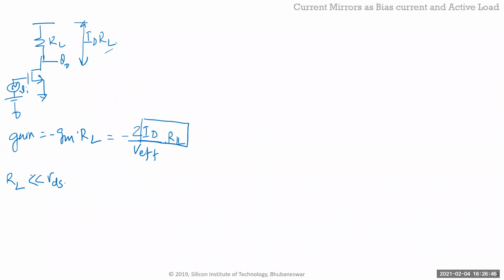Anyone on the call, what's the problem? I mean, you can design it. When I say problem, it's not like you cannot design it at all. You can design it, but two things are coupled, right? So why is that a problem? My small signal gain is coupled. This voltage drop is coupled, right? So why is that a problem?